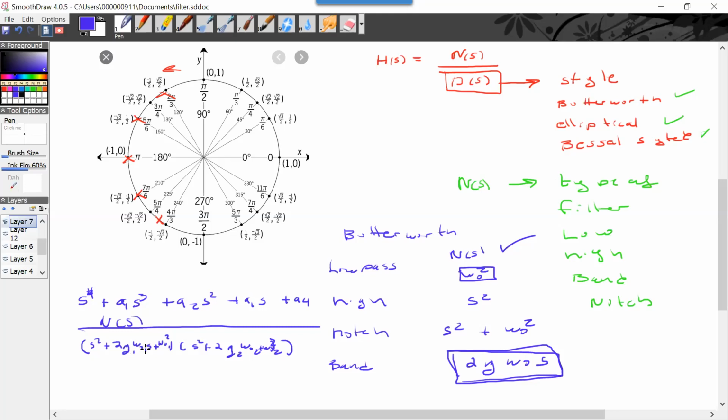So a fourth order is really just 2 second orders multiplied by each other. So if you know what a damping coefficient is and you can deal with all of that, well, you can deal with a fourth order. And then a fifth order would just be, you know, s plus some omega A, right? I could have a sixth order where I have another second order, then making it seventh order, I could just add in one real pole. And that's what happens, is that the first order,